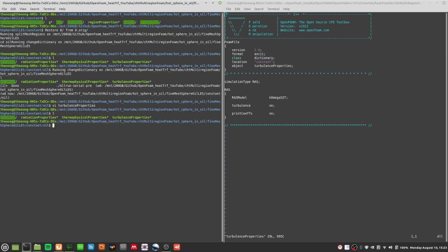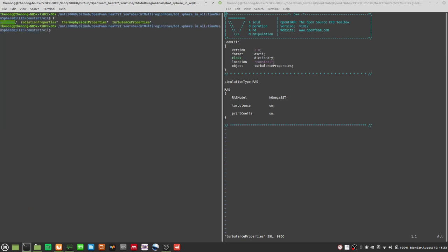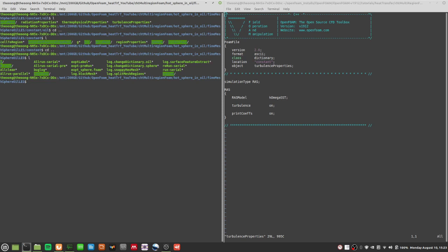As for a dynamic Prandtl number, as of now OpenFOAM doesn't really have the capability to do that. Similar to how we have a dynamic LES model, for dynamic Prandtl numbers you have to code it in yourself. It's not natively available yet in this version of OpenFOAM.